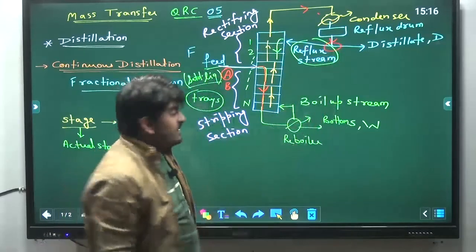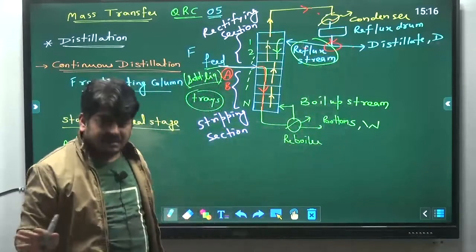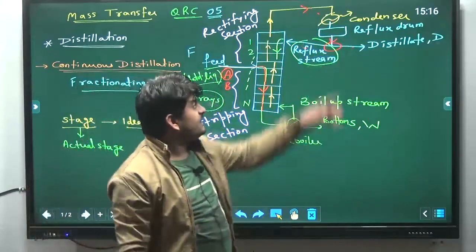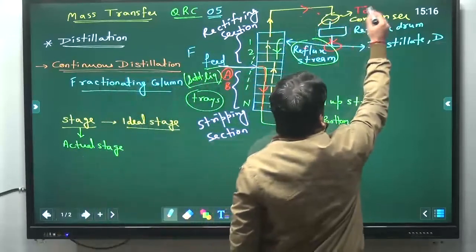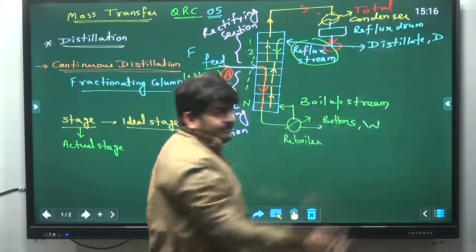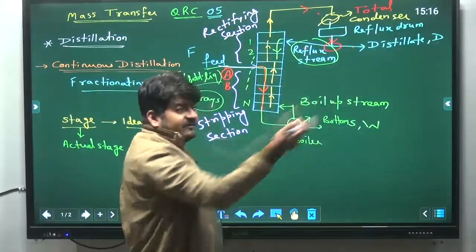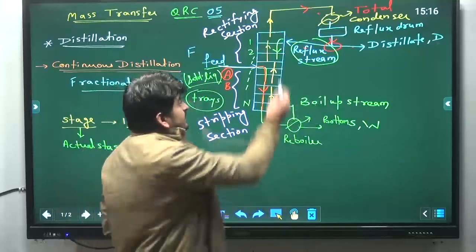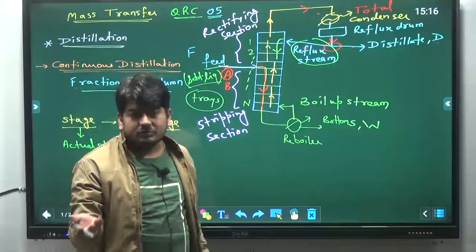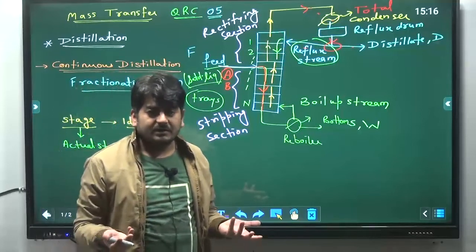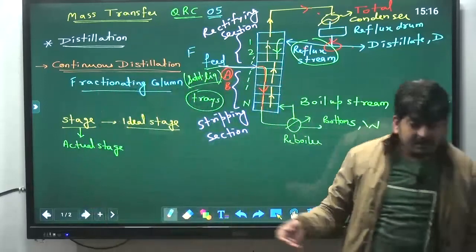This is just a splitting of the liquid stream. So the composition of these three streams is usually the same when we are operating with a total condenser. So this liquid already has a large amount of A. When this liquid comes in contact with the vapors, some more A transfers, like we discussed with the Reynolds analogy in some class.